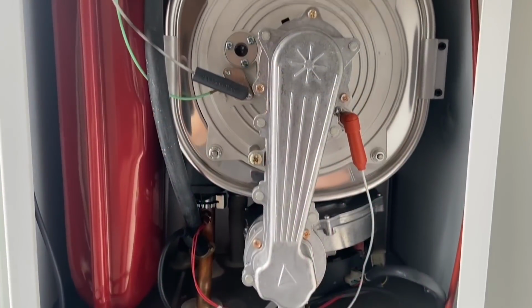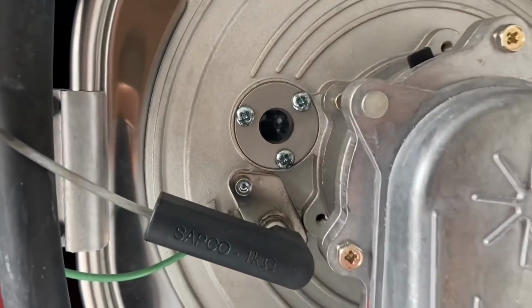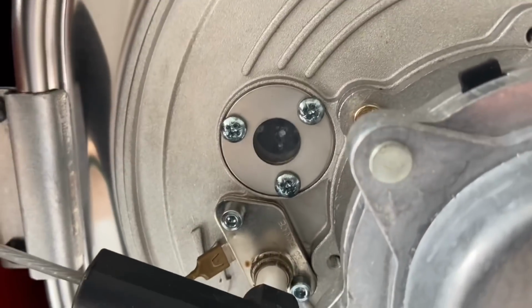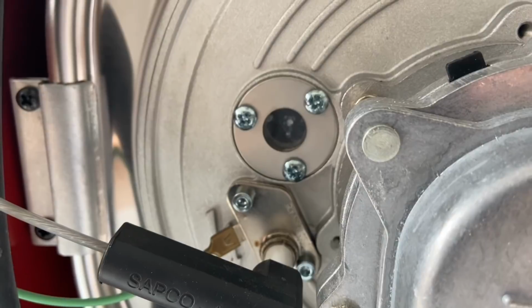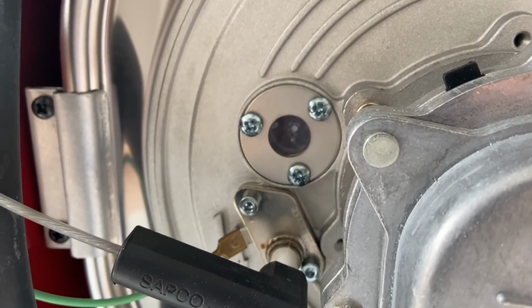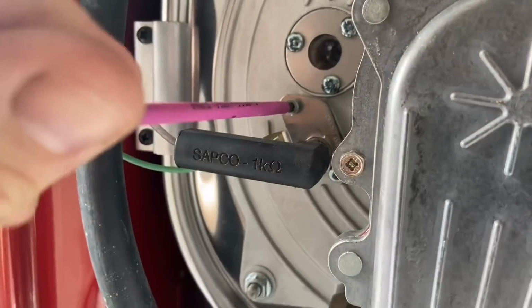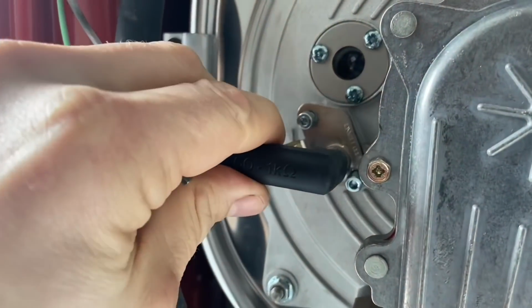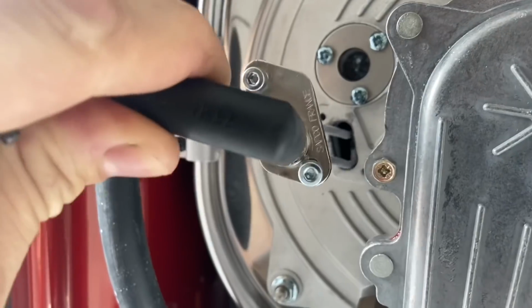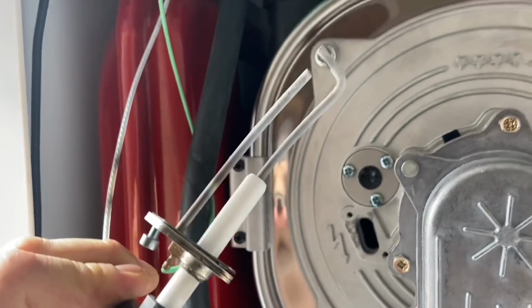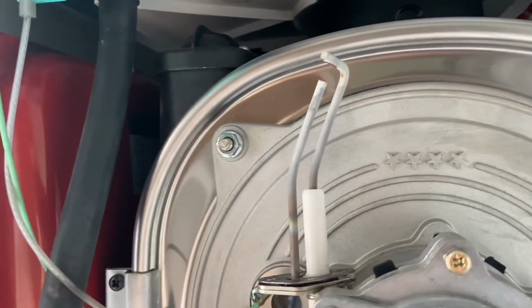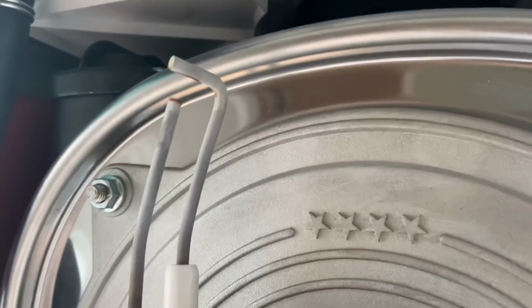Right guys, this call out was because the boiler had started making a noise that it hadn't done before and the customer was worried. Basically the noise when the boiler was firing up, a kind of vroom, like a rushing sound, is caused by the delay of the gas lighting, and that can be down to the ignition electrodes. When I take them out, I'll show you, there's a distance between the two, and that's where the spark jumps across. And because they're in heat all the time, they can bend out of shape.